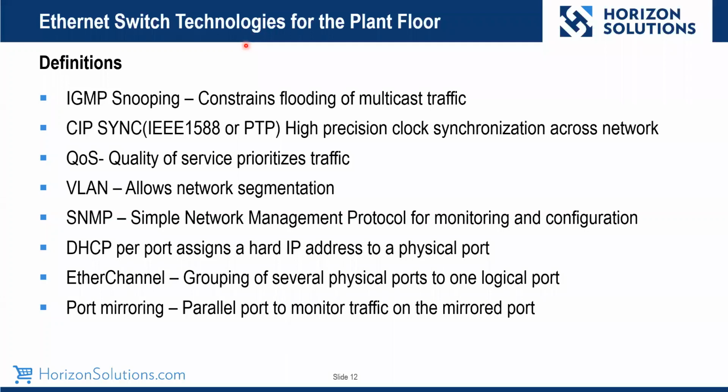Another thing that's pretty cool is this thing called DHCP per port. What that does is it hard codes an IP address to a port. So why would you want to do that? Say you have a drive in the middle of the night, the drive dies. You need to replace it. So the maintenance guy or controls engineer goes out and puts a new drive in, wires it up. What this does, it pushes the IP address down to that port, because by default, our products come with DHCP enabled. So without going through and using the BootP server or hard coding in, we could actually push an IP address down to that device.